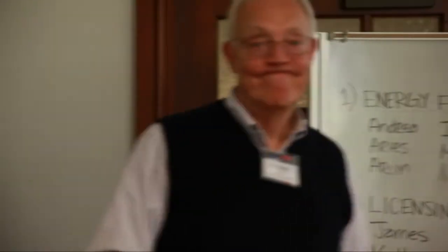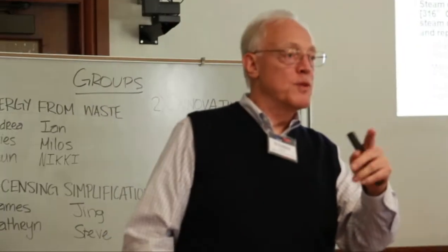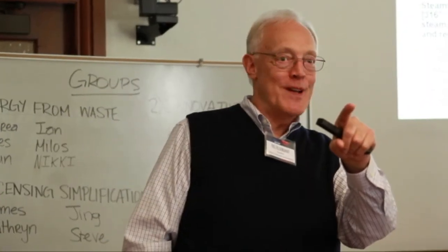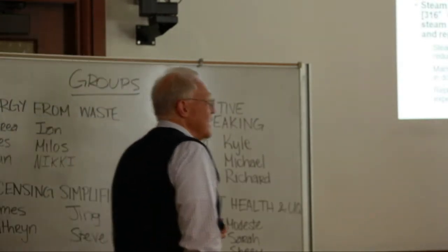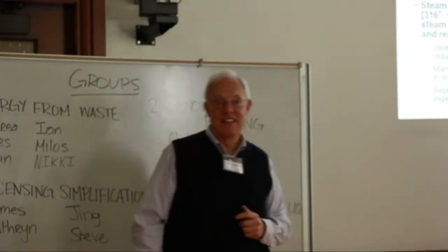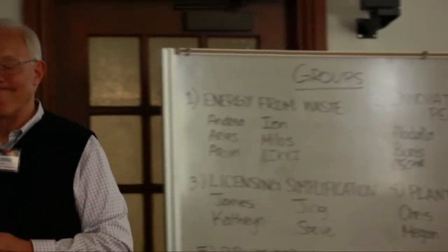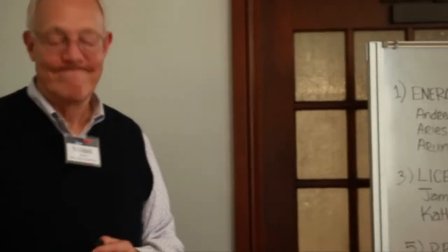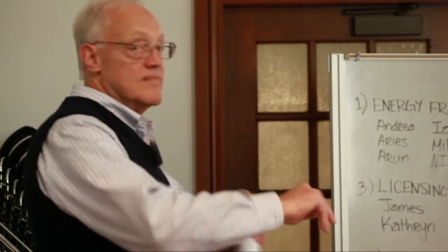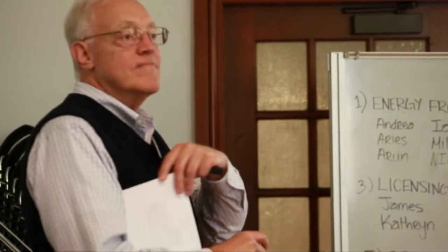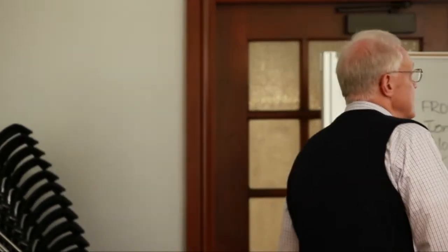Well, Phil, if you don't mind me interjecting as well. Yeah. By the way, we won't have 100% agreement on some of this perspective. No, okay? I'm actually in agreement. A very interesting subject, not related to nickel alloys, but the stainless steel 304 used in BWRs. Why stainless steel 304 when General Electric and industry knew since World War II that 304 stainless steel has stress corrosion cracking problems?